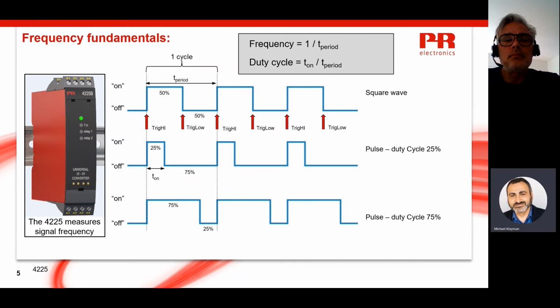Frequency signals can have different shapes. The sinusoidal shape shown on the last slide is commonly created by AC power and tacho generators. However, most frequency signals have a different shape. It usually does not matter what shape the frequency signal has, as long as the signal changes in a repeating pattern so that the period of each cycle can be measured.